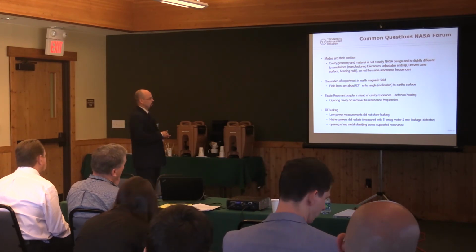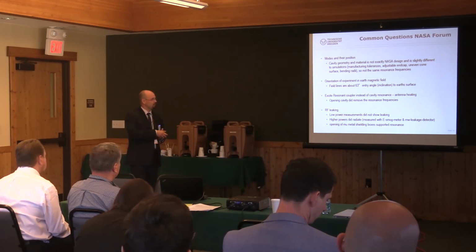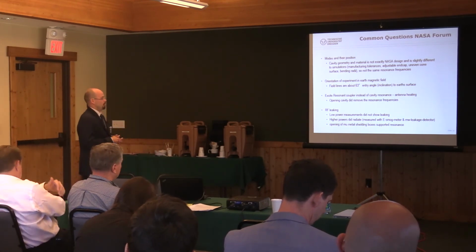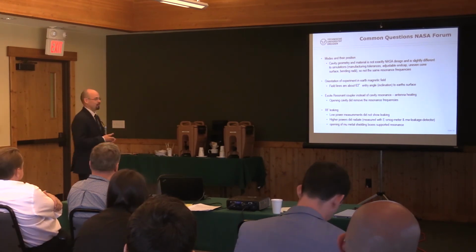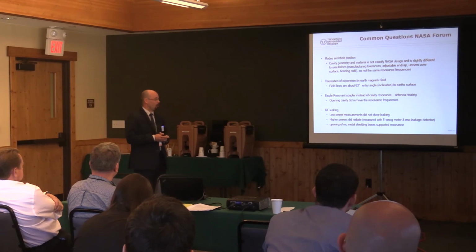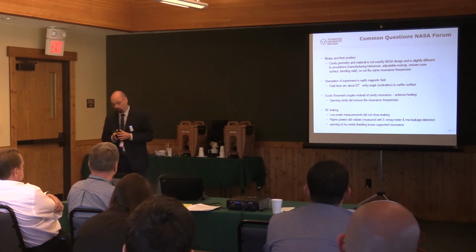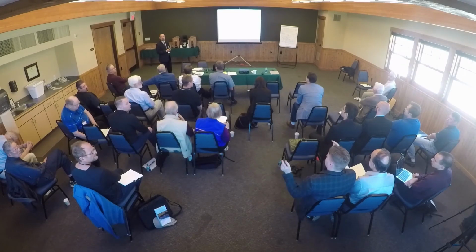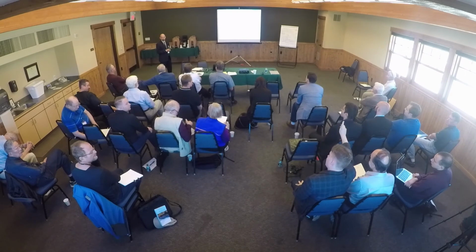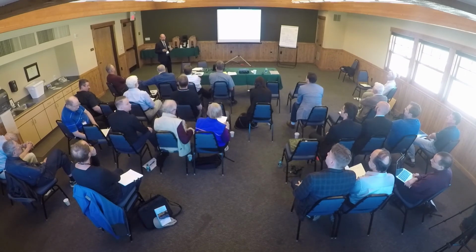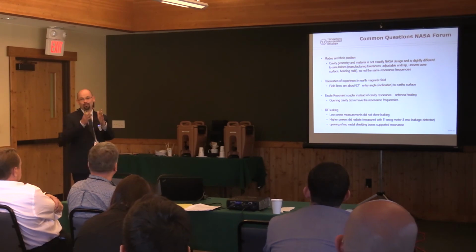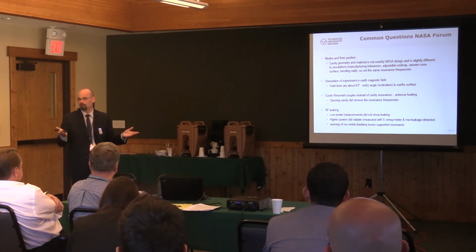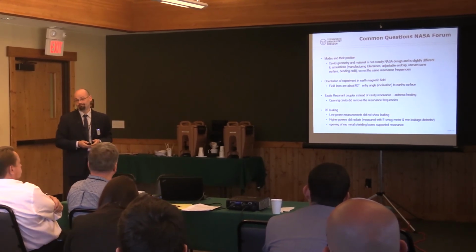Well, another point was the critique that I excited resonant coupling instead of a resonant mode of my cavity, and so in this way I just heated my antenna. Well, I can't say that is not the case. I'm not very convinced that it's possible, but the easiest way to test for that is, while in resonance, just push on your cavity, and see if the resonance frequency moves. Another way to test it is to open your cavity, look at the frequency you want to look at, and if the frequency disappears, it was a resonant frequency of a cavity. I did this, and I used such frequencies.